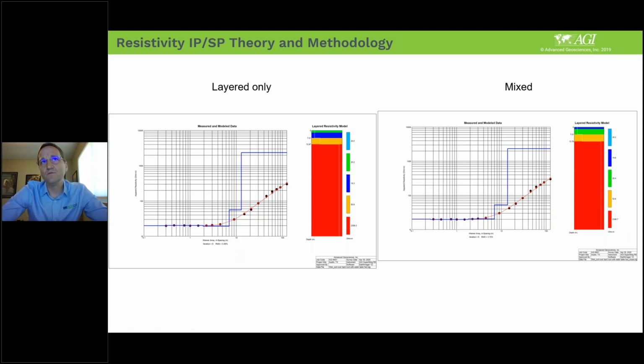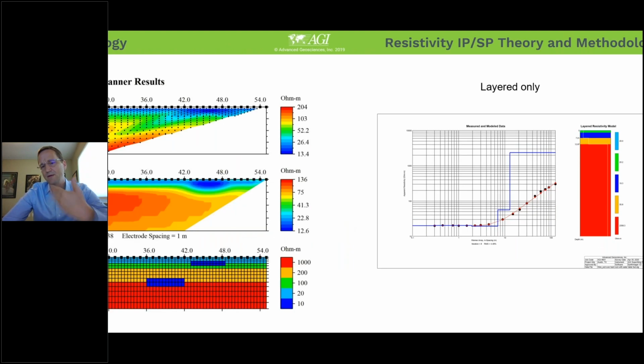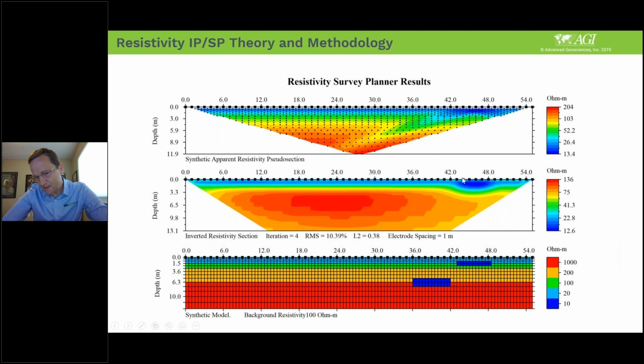So to account for it, you would have to take many soundings, many Wenner, hundreds of them. So in our industry, we automated it, and that's why we have these 56 electrodes scanning back and forth, so we can pick up those pockets. And this is an automated system where you lay out a cable with 56 electrodes, and then we end up imaging those. These are actually a little bit difficult to see because they're right next to each other. It's kind of amorphous, we see this smooth response, but we know there's something mixed over there. So that would be a good place to explore further.